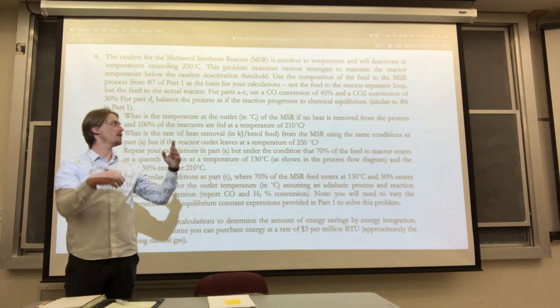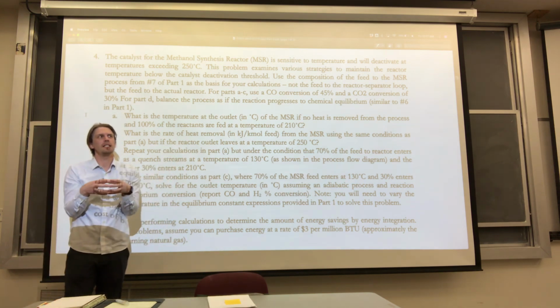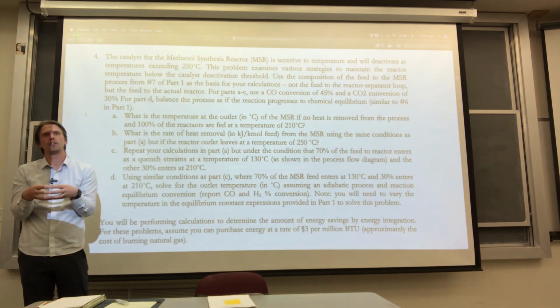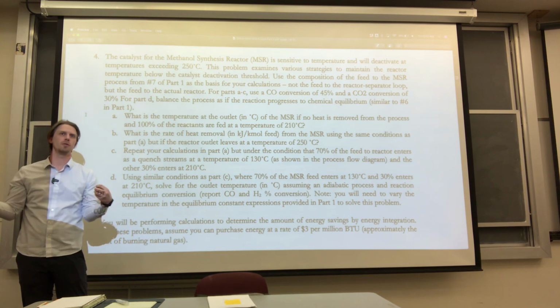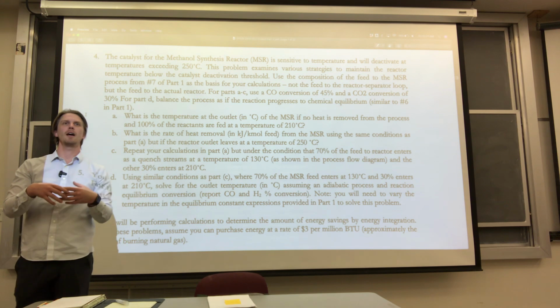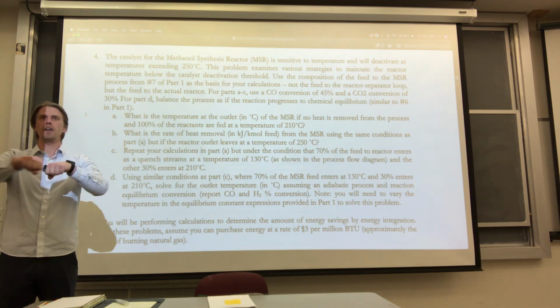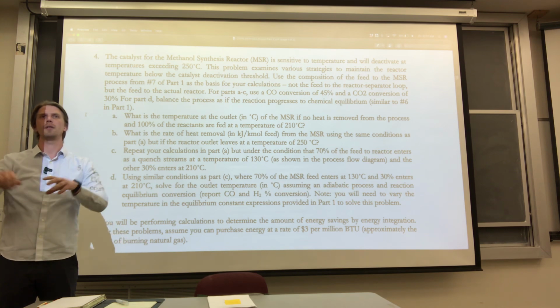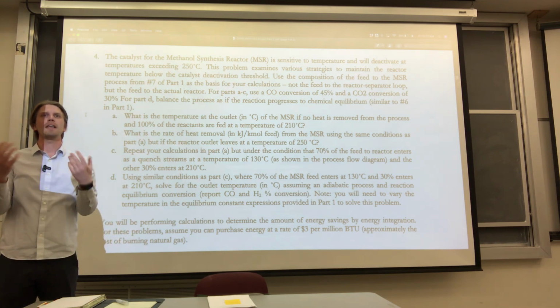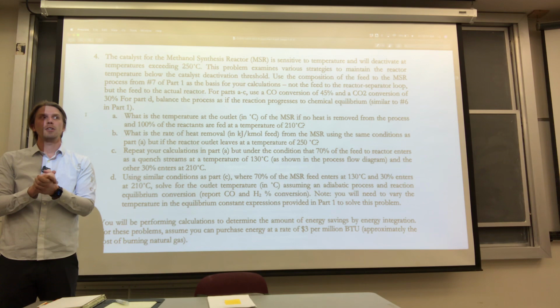So what happens is at these high temperatures, these really delicately constructed alloys, the metals can diffuse, right, and they'll phase separate. So what normally would have been like an aluminum oxide alloy or some sort of iron alloy, it'll just phase separate into pure iron and then whatever the extra material was. And then the catalysts don't work so good, and you have to replace it.